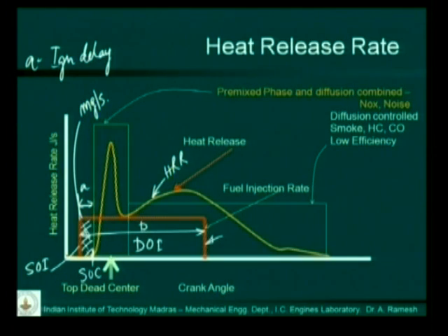So you find that there is a sudden rise in heat release rate. The heat release rate shoots up like an explosion, and immediately falls down when all this is burnt. But fuel injection is continuing. So the fuel that comes after the start of combustion is coming into the cylinder at a high temperature. The temperature of the cylinder has already gone up, so this fuel does not suffer a big ignition delay. As it comes, it tries to burn.